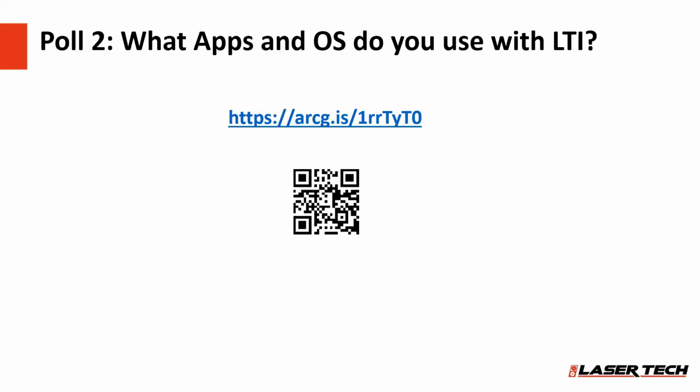So while we're waiting, Jay, there's another chat question that came through about working within a trench. And this can be another great application for the laser. Trenches are often dangerous to get into. So you can stand on the rim of the trench in a safe location, grab your GPS coordinate, and then measure down into the trench and get that critical scene location or something like that.